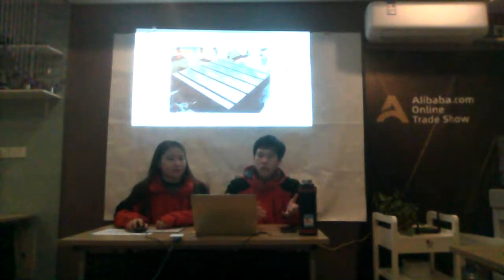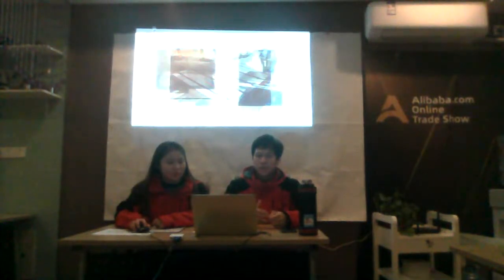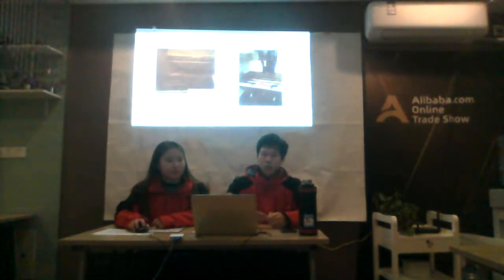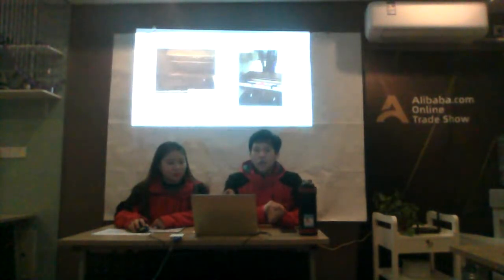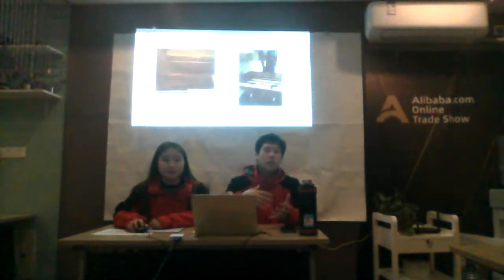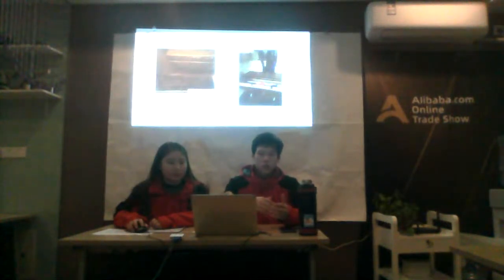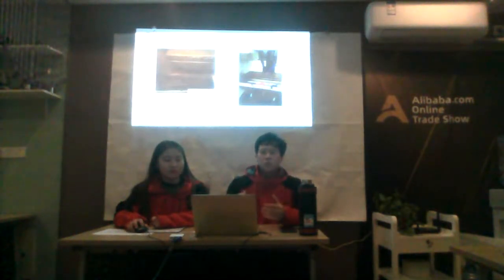And this one shows you the moving axis of our work table. It can move by X and Y axis. And this one shows you the detail of our travel axis. So as you see the photo on the left, that is our travel axis gear rack protection. So it will prevent the material scraps from falling down into the screw guider and damaging the machine's travel persistency.